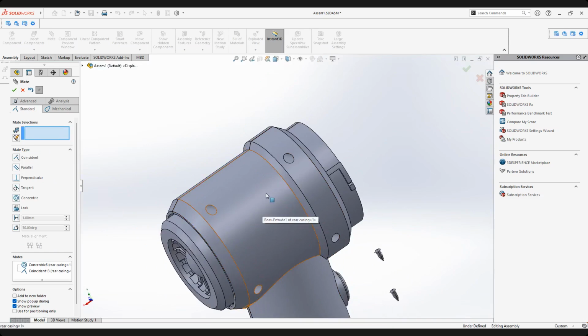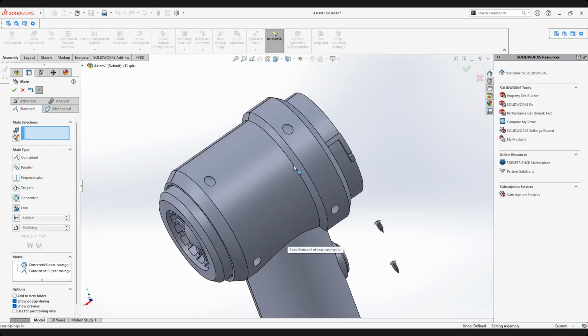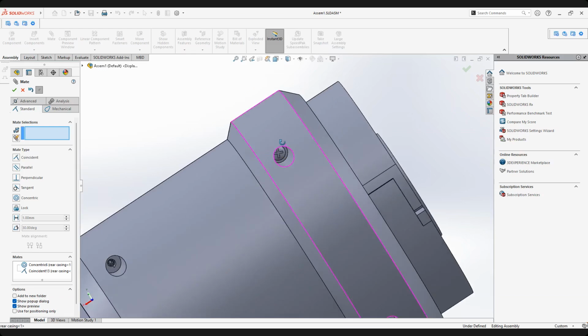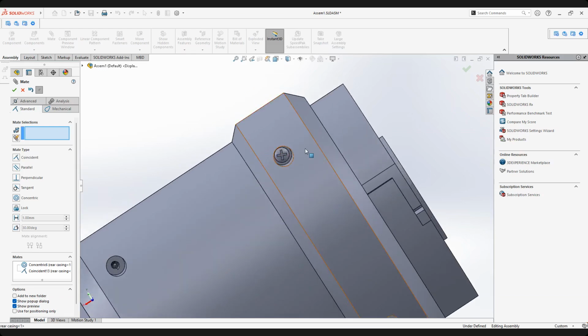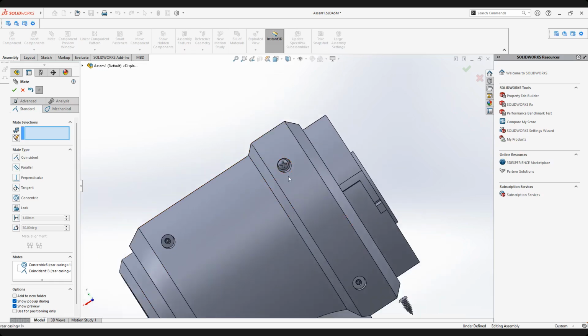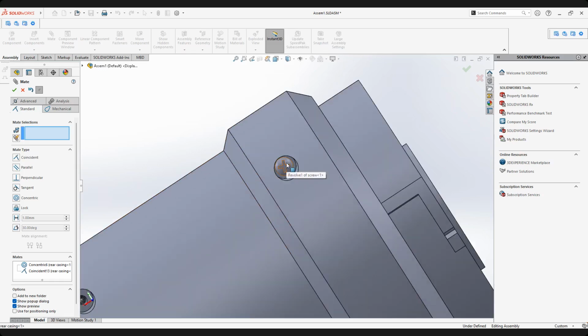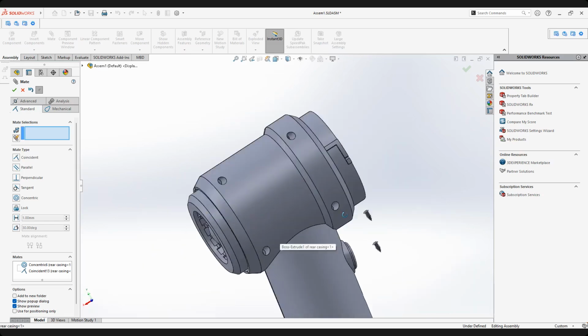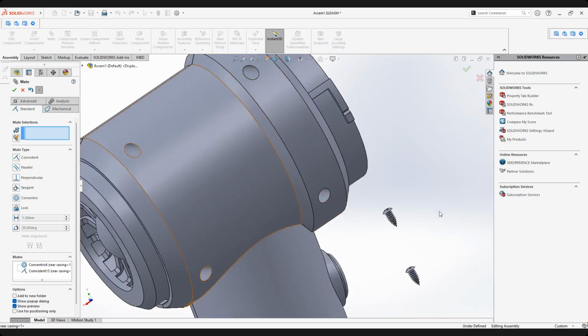I don't have to do 4 more times, but if you mirror the screw thread, you have a left hand screw thread or right hand screw thread. When you mirror it, the mirror representation of your screw will become a left-handed screw. Understand? The thread will be mirrored. That is wrong, because screws have right-handed screw thread, so you cannot mirror it. Okay, so you have to do it manually like this.